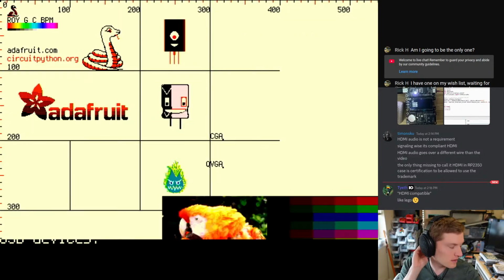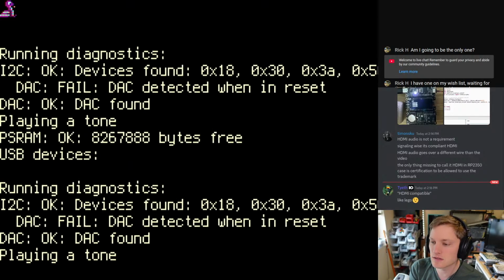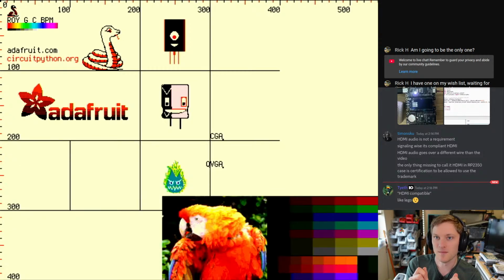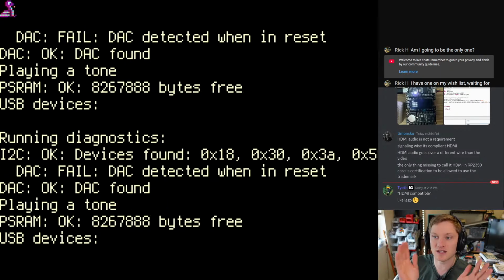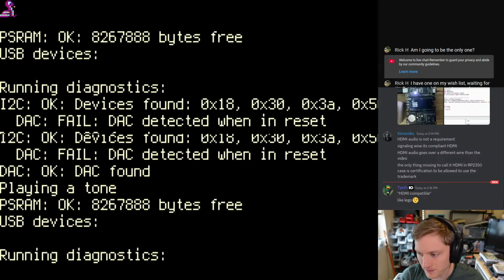One thing is that we're using the HSTX peripheral on the RP2350 to generate this. And it has to expand colors from however many bits we give it out to a full 8 bits. And it just zero pads it. So if you're doing only a single bit, it's going between 00000000 and 10000000. So you're not actually getting the full range, and different things convert those colors differently. In this case, I'm running this at 8-bit color because I'm running in full resolution.